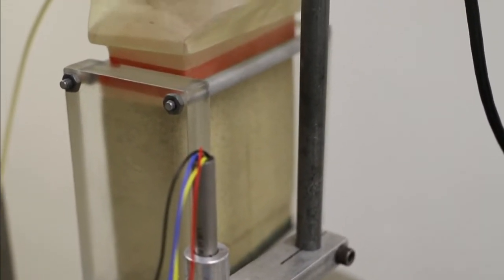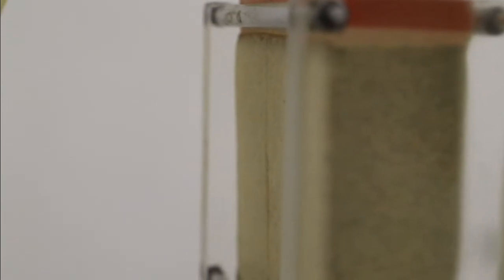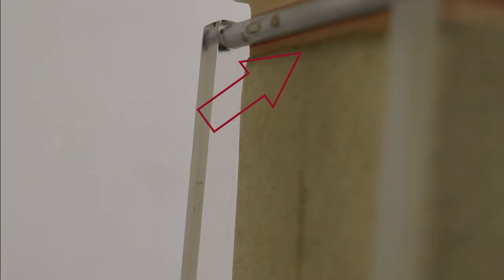Now if we move around to the side, do we see any evidence of that through the plate? There's a little bit. You can see that it sticks out about an inch above the bottom cap on the right side. It's starting to daylight there. And if the failure plane is there, it must be running steeply up to the left, probably right up to the corner with the top cap. It's kind of hard to see that at this point, but we'll track that, and when we take the plates off at the end, it'll be very obvious where that is.